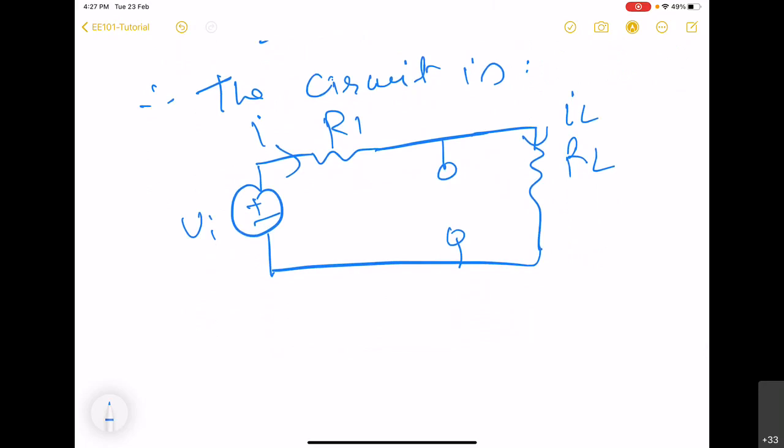Right. So here we can see that when this Vi increases, the current is going to increase, and this VRL, this voltage is also going to increase. And keep in mind that this voltage VRL is ultimately going to be the voltage that Zener will experience, right?